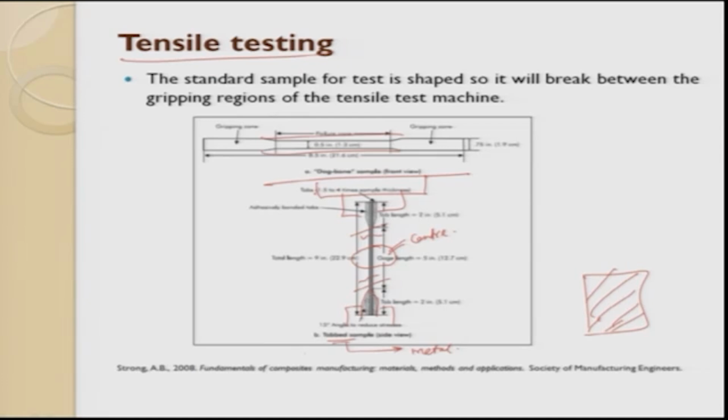So people start doing it. One way of doing it is you take the sample, put it inside an atmosphere, maintain it at humidity 60%, 70%, 80%, and then come here and do the ASTM standard tensile testing. The other way around is you do it simultaneously, and they also try to do the testing like that. So here the strain rates are important.